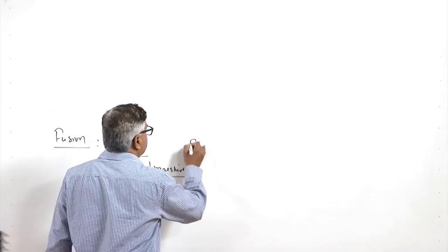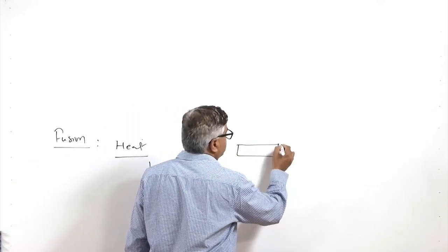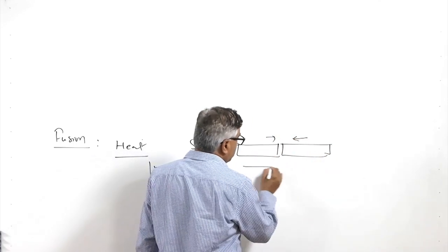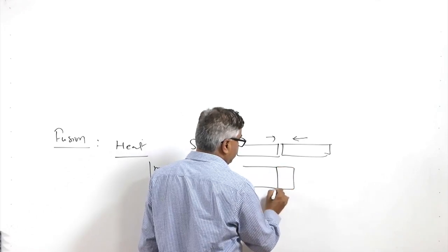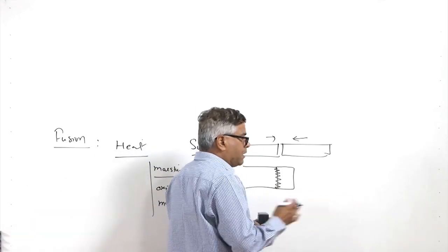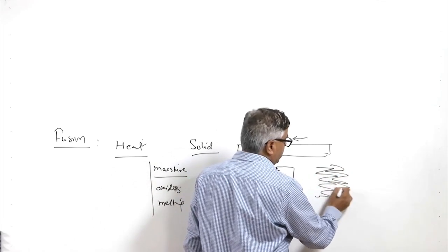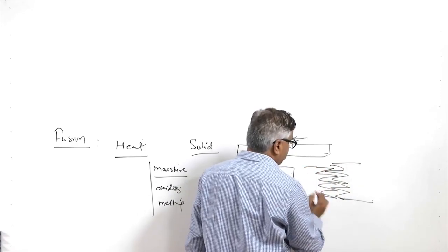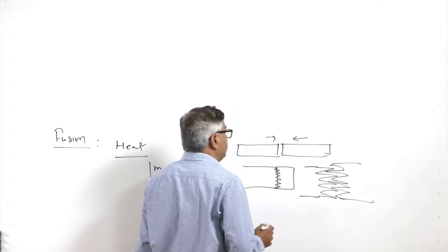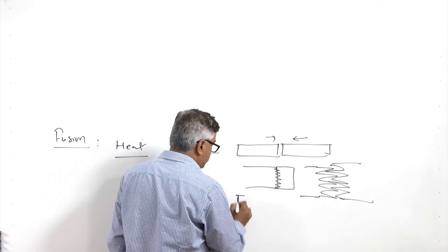If we consider the solid state joining processes, wherein the metal pieces are to be joined in the solid state, under pressure the two are brought very close to each other, so that the faying surfaces touch each other very firmly, and the metal to metal contact is established through the deformation of the peaks and valleys at the surface. So, like the peaks and valleys are present at the surface like this. So, peaks and valleys from both the sides will be getting deformed at the interface and will be leading to the complete metallic intimacy.